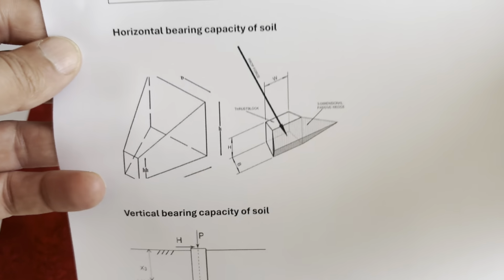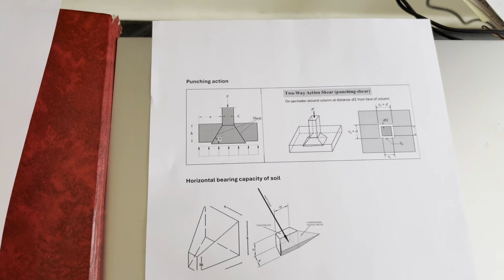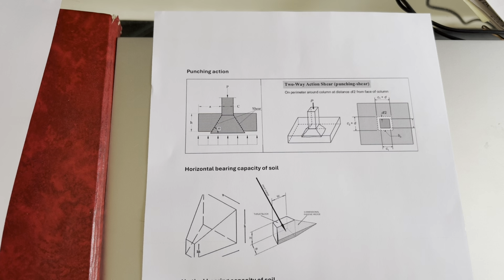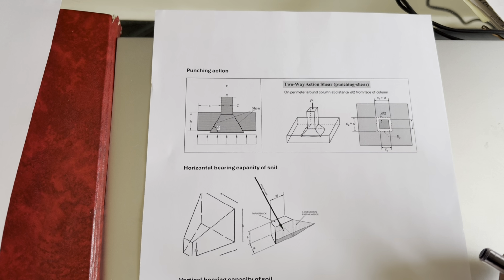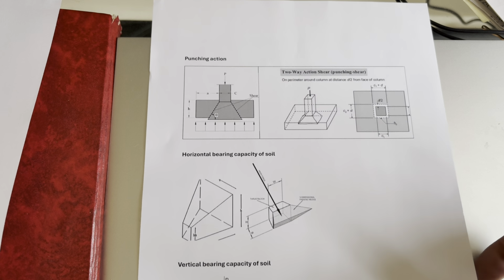So the last part is some very basic and general principles to design thrust blocks, anchor blocks. You know that there is no specific design code, or the literature is not sufficient for thrust block design, because it is just something general. It relies on the basic principles, but we need to make sure that the basic principles are all met, and we are confident enough to take the serviceability limits and the ultimate state limit.